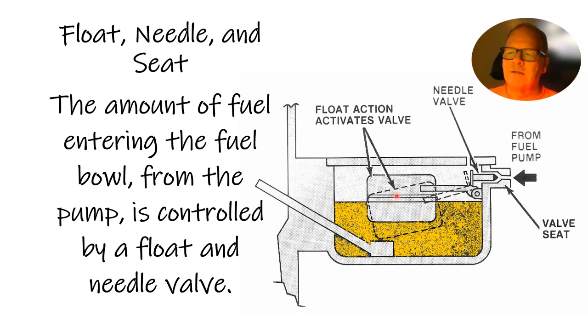Some of these floats would be brass, soldered like a shell, and more of them, as time went on, became a sort of black foamy thing. It was solid foam, but it would float, and it would close that needle off every time. Whenever it would come up, it would stop it, kind of like a commode float. Whenever it comes up to where it's supposed to be, it maintained the level in that reservoir.